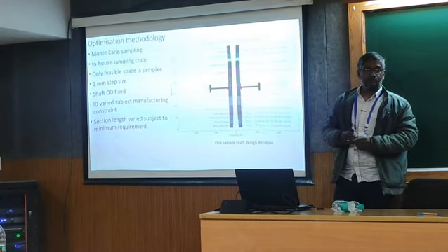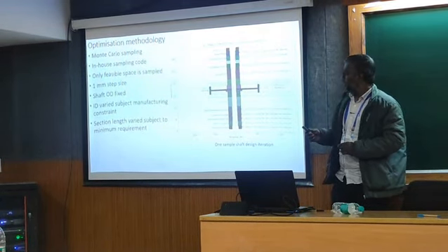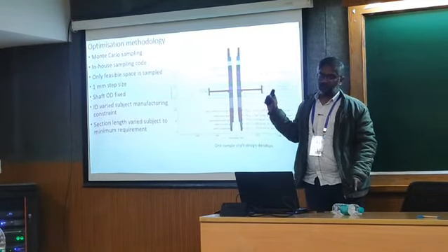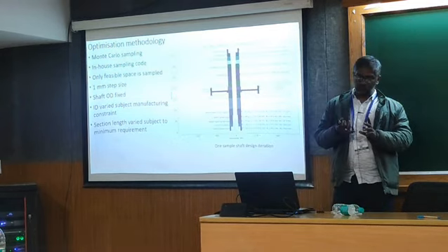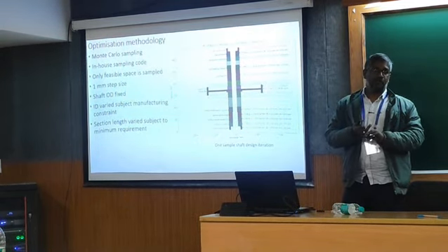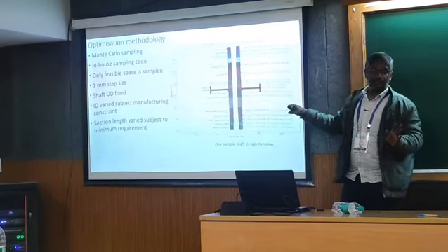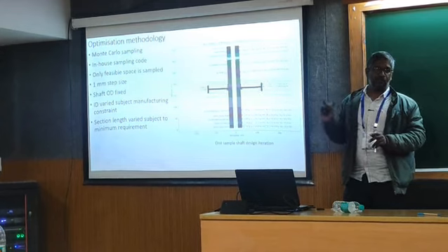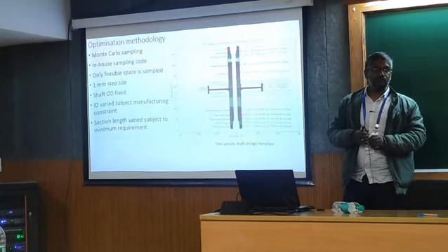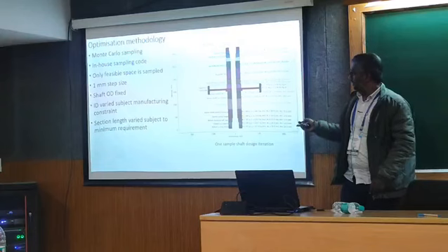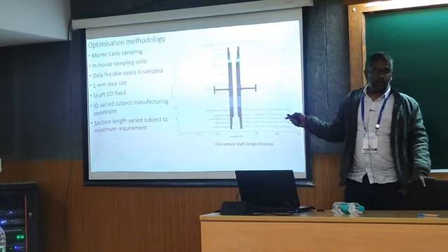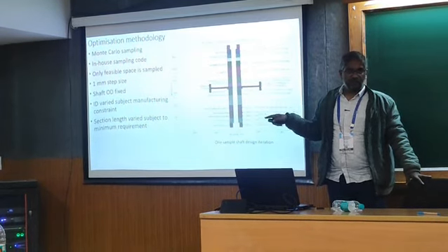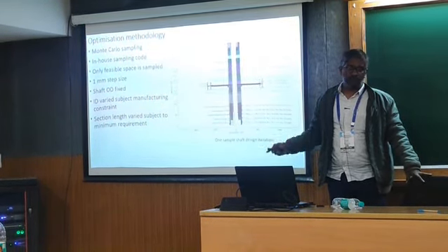What is the specific application for which you are doing shape optimization? Because it depends on the specific application. Right now this rig is to demonstrate stable levitation in the presence of gyroscopic precession and nutation. Once controller is proven using this rig, same controller will be used for a flywheel energy storage system for AOCS application. What controller? This algorithm is LQR with Kalman estimator. Controller is a DSP board, STM32. DSP. Yes.